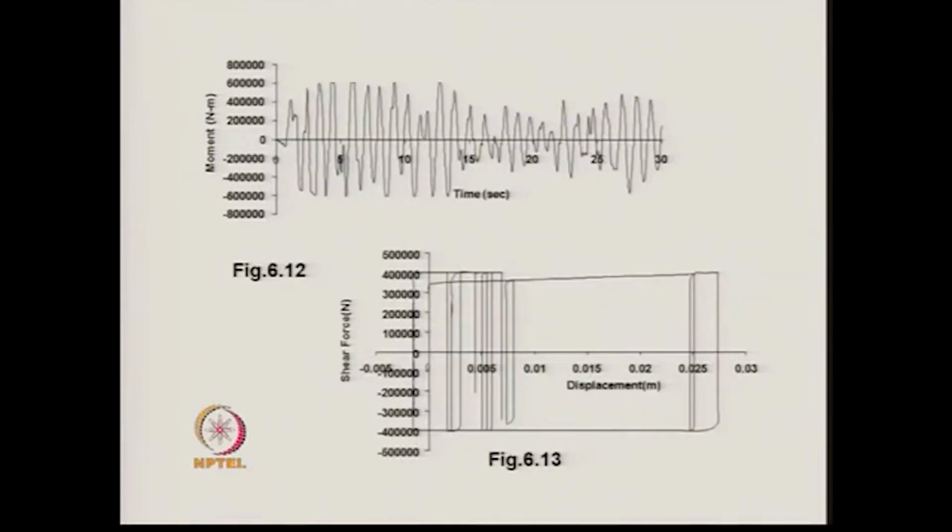For the second case, where we had a bilinear curve representing the force displacement relationship, the bending moment plot shows that at the peaks the values do not remain stationary over the delta t time. It is slightly inclined, showing a small variation, because of the stiffness that we find after the yielding, the stiffness represented by Kd.